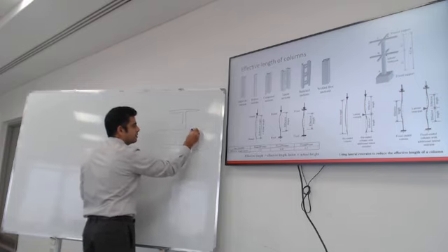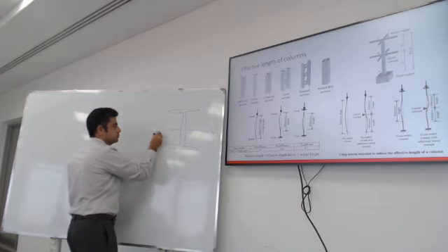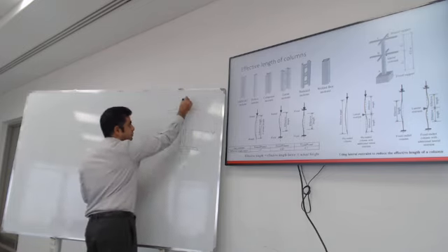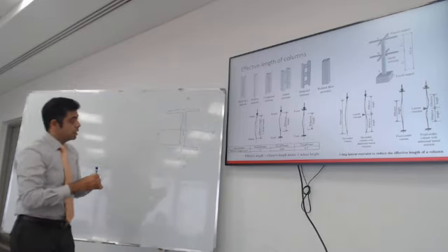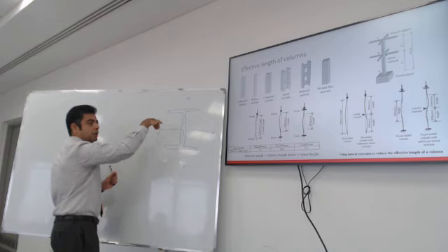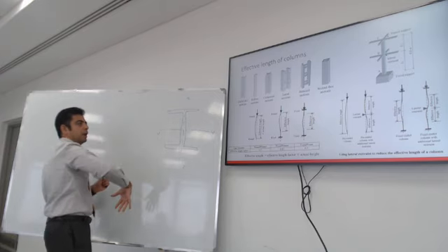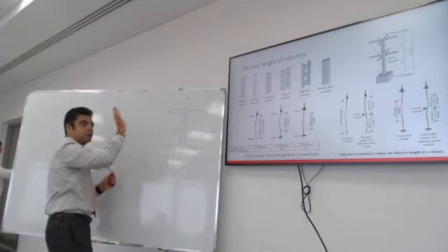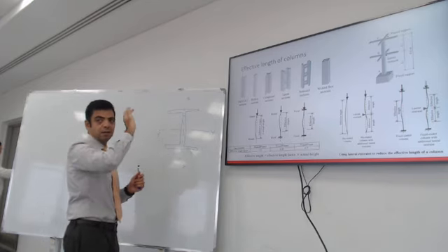The strong axis, let's call it Y, and the weak axis could be Z. If the column wants to buckle about Y, you use the effective length in the Y direction. If it wants to buckle about Z, use the effective length about Z.